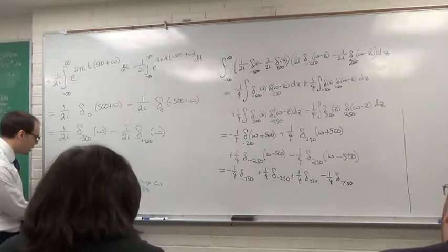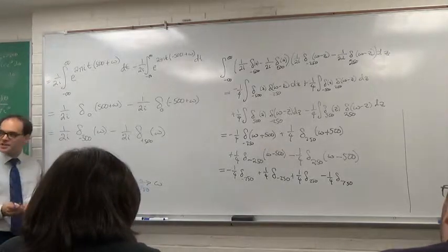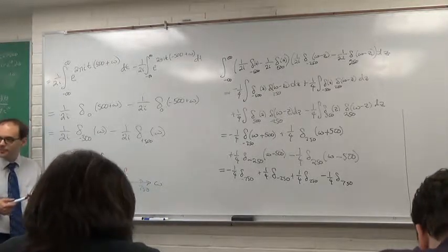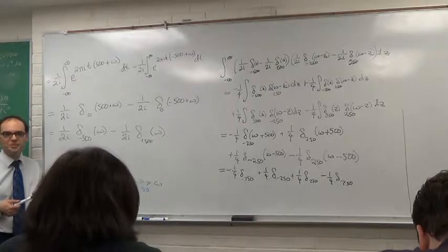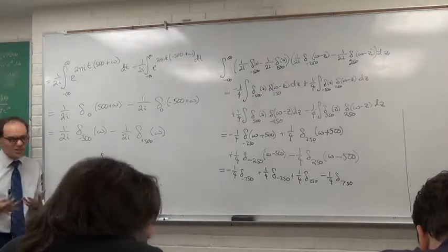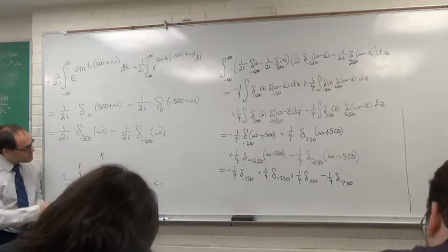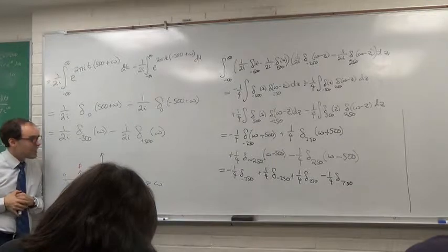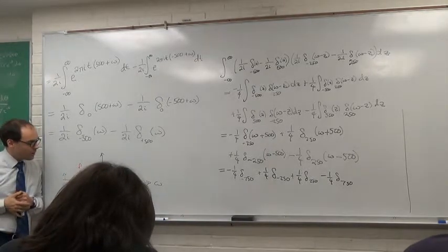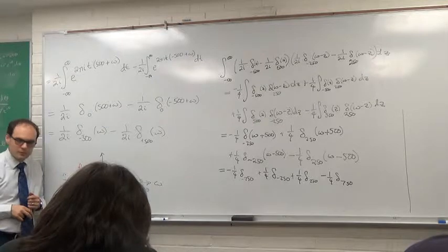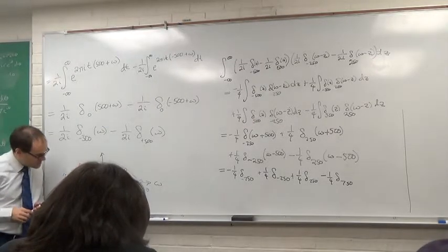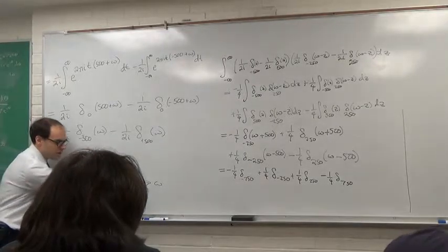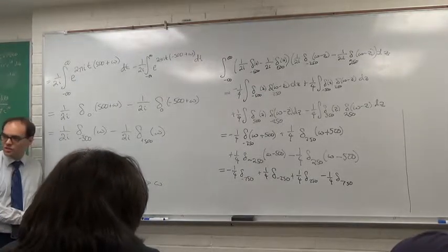Got it. And if you look at it, wait a minute, that's exactly where that trig identity said they ought to be. So convolution actually recovers that trig identity for you. Not saying this is an easier way to do it by any means, but it certainly works. It's at least self-consistent. So what does this mean? If I take two tones and multiply them together, your ear will hear musically two tones. One of them is going to be the sum and one of them is going to be the difference.